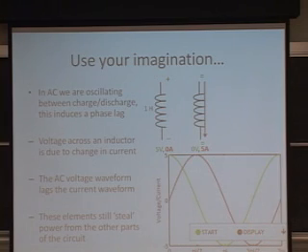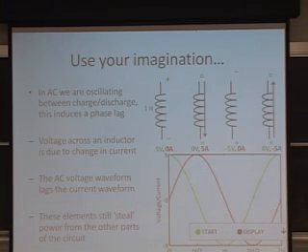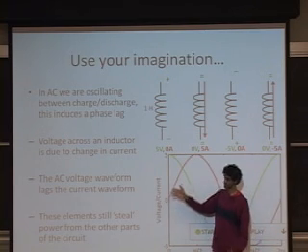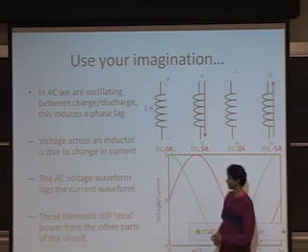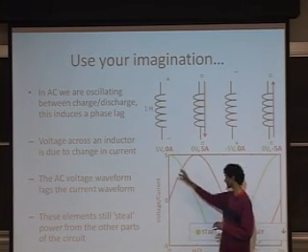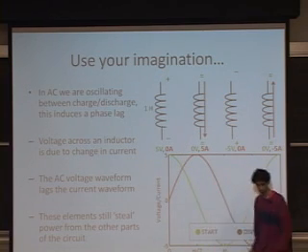And as we go through the cycles in this inductor, we get current flow and then no voltage change. And then the backwards effects start happening. So we get positive voltage difference and a negative voltage difference, and in between we have current flowing forwards and backwards. Again, that's a charge and discharge-like scenario. But here, because the relationship is inverted, we have now instead the voltage lagging the current waveform.